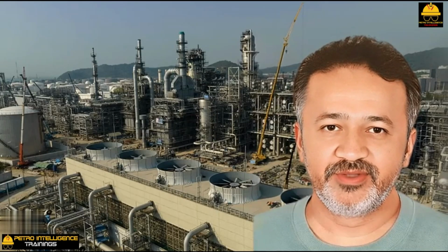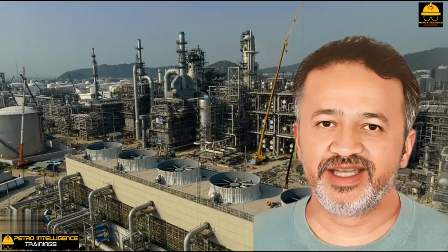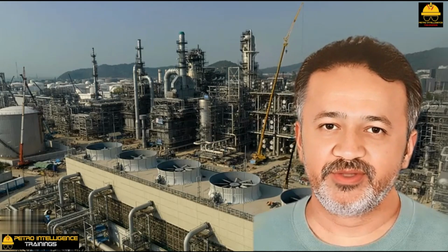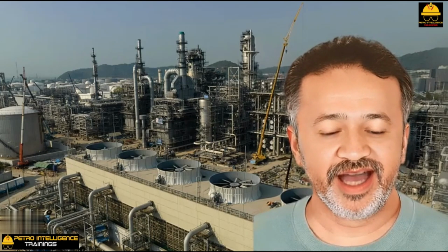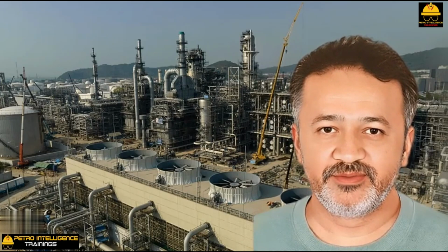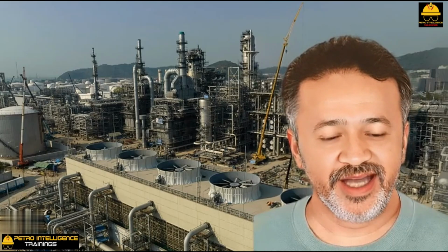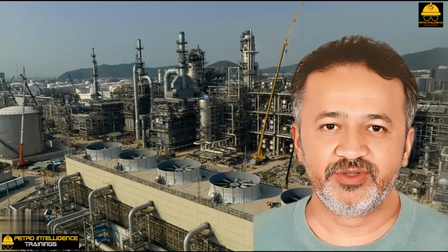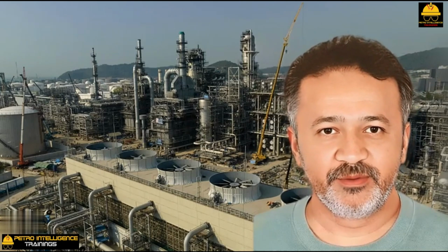Sweeping the underside of an air cooler tube bundle. A fin tube bundle acts as an air filter. Air is drawn up through the lower two rows of fins where much of the dust, dirt, bugs, and moths are filtered out, and thus restricts airflow. Water washing is the most effective method of removing these deposits. However, many of my clients will not water wash hot air cooler bundles while running for fear of pulling out the tubes from the tube sheets due to thermal contraction of the tubes.